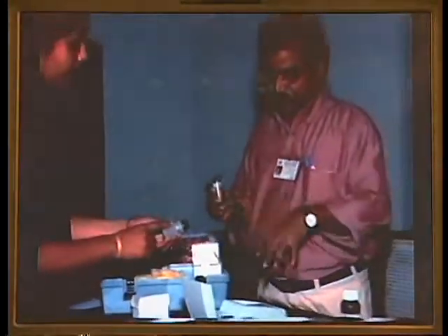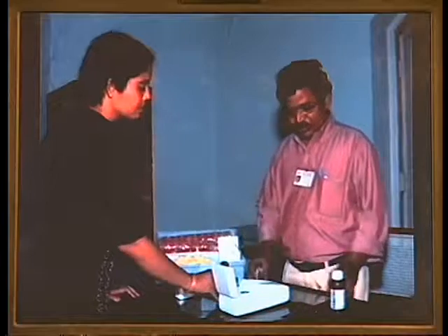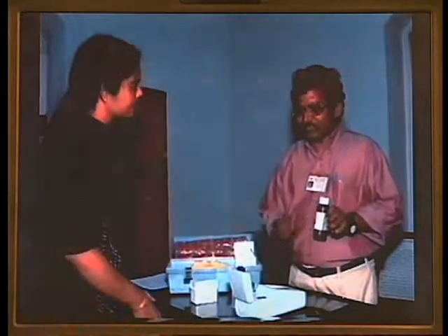So let us go and see in a laboratory how the turbidity is measured using a turbidimeter. Here we have a turbidimeter. There are some ranges: 0 to 1000, 0 to 100, and 0 to 10. We can standardize this instrument in these ranges. If the turbidity is more, you have to standardize the instrument using the standard solution.